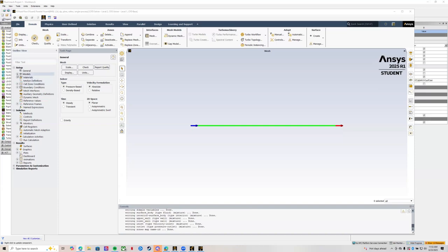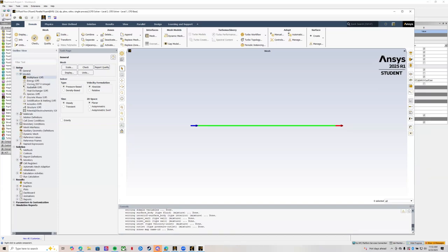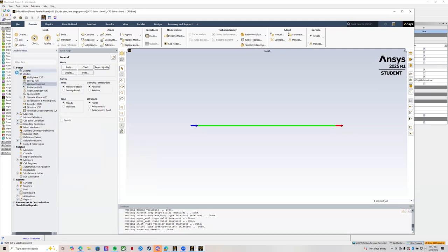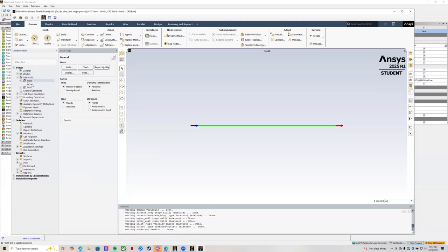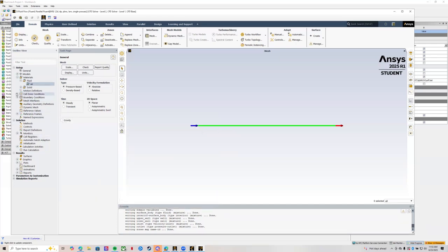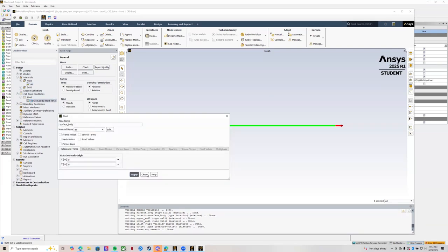This is where you will make the boundary conditions and all the other things that make the flow. First things first, make sure the viscous model is laminar. Change your fluid to air, or make sure it's air. Go here so you can change your density. For the first flow, we chose a density of 1 and a viscosity of 1e-5. This gives us a Reynolds number that's around 945.